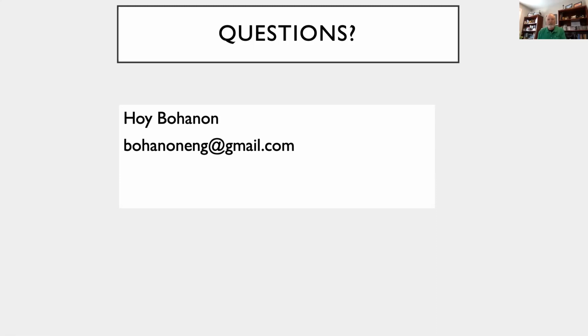it was proposed, and the committee decided, both the 62.1 committee and the 170 committee that dealt with hospitals, that they didn't want to get into that at this point in time because of engineering problems that might be caused. I totally agree. I'm the one that submitted the change to put in a minimum. The question is, why did it go away? The reason why it went away is that the comfort research that happened back in the 1990s indicated that people were comfortable with a low humidity, so that went away.